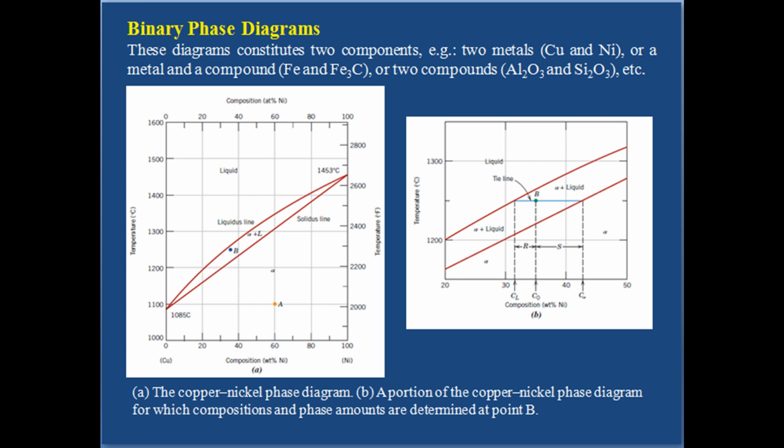It is also to be noted that all binary systems consist of only one liquid phase, that is, a component is completely soluble in the other component when both are in the liquid state. Hence, binary systems are classified according to their solid solubility. If both components are completely soluble in each other, the system is called an isomorphous system. The extent of solid solubility for a system of two metallic components can be predicted based on Hume-Rothery conditions summarized in the following.